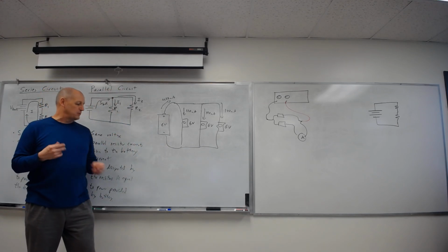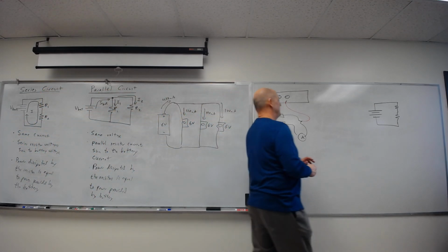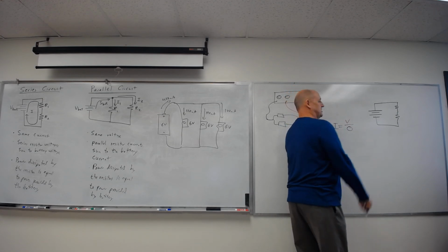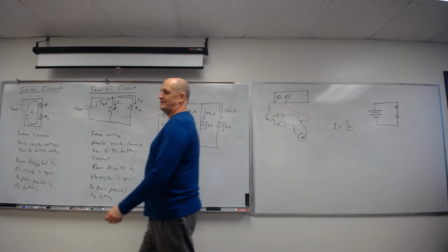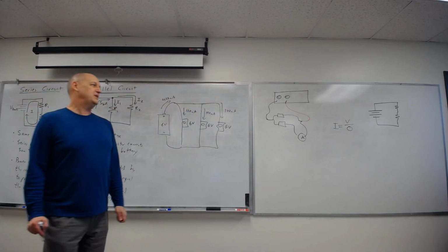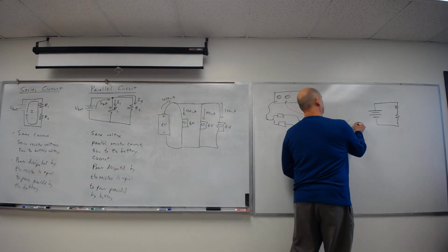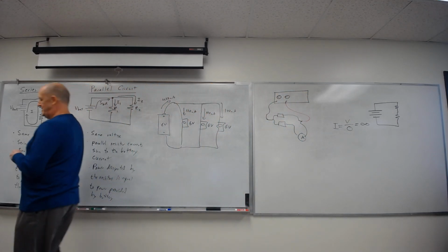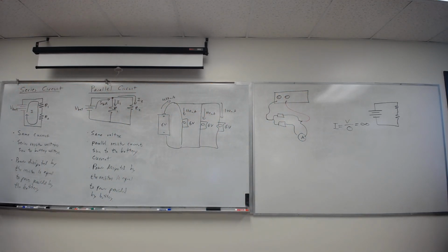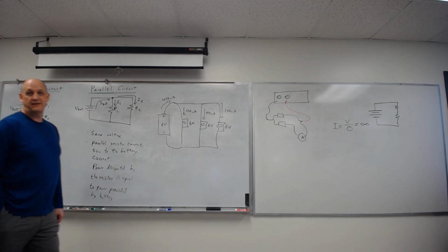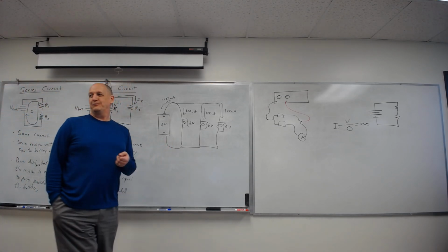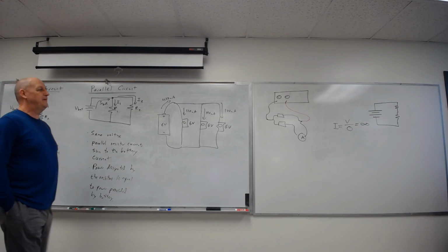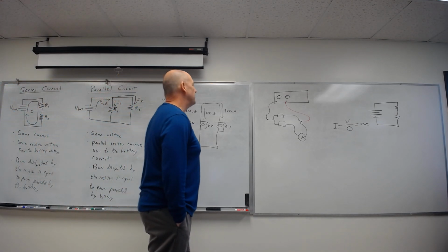There's nothing good there, because of Ohm's law. If you do that, you're saying, take my voltage and divide by the zero resistance in my ammeter, so please give me an infinite amount of current. I really like infinite current. We can't do that. This can give you enough to blow the fuse. In fact, some of these in here can actually give enough to maybe hurt you, which otherwise can't hurt you, but that might. Probably not. Don't do it.